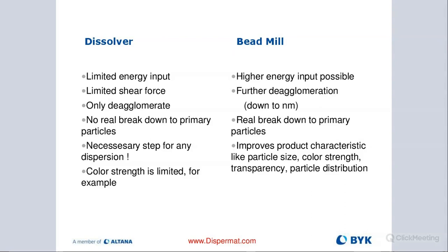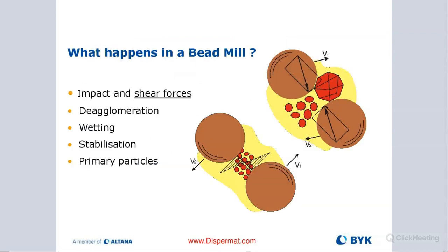So we want to make sure that you measure that, maybe with a grind gauge, before you start milling to know exactly, hey, this is now a good time. Now we can start the milling process with the bead mill.